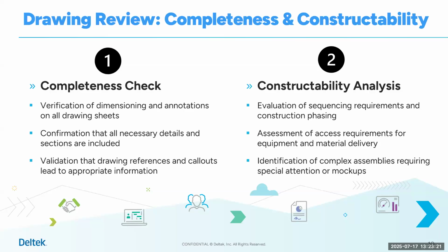There might even be some coordination drawings that are part of the project, where all of the contractors from the different disciplines have to put down on the coordination drawings their different systems to make sure things don't clash, to find out where you might need to put access panels or where access panels can go, where the lighting falls within the HVAC ductwork. See, these are things that a CA person would be able to review for completeness and constructability.